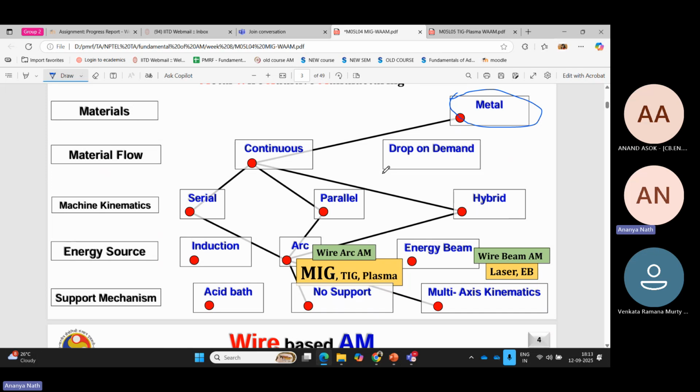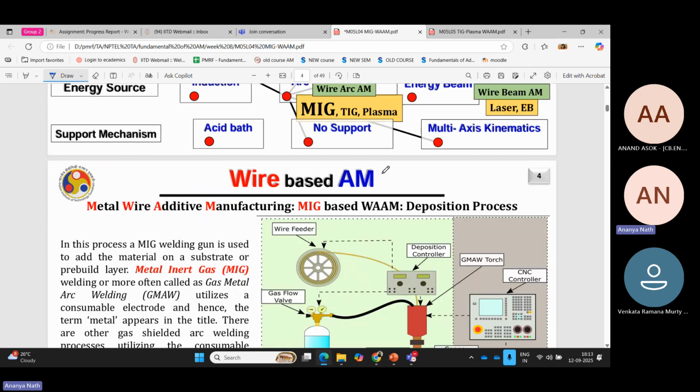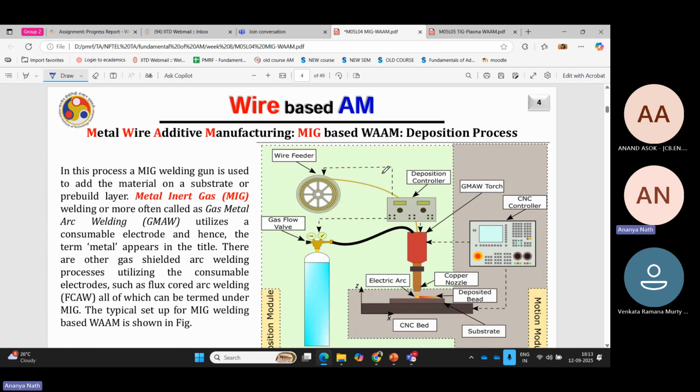So if you are printing it with a CNC machine with 3 degrees of freedom, obviously, in the case of high overhang angle and overhang length parts, you have to put the support structures. But if you are working in a robotic system where the robotic arm is having equal to or more than 5 degrees of freedom, then it's good to go to print parts with no support structure. The overall concept I have already told you.